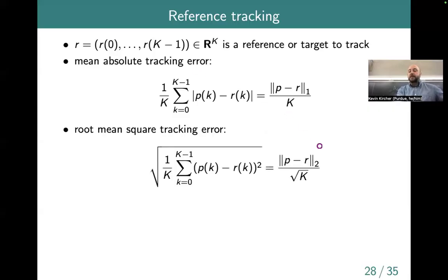Another way would be using a 2-norm approach rather than a 1-norm approach. Here we look at the error and square it. This says it's bad to overestimate, and it's also bad to underestimate, so we square it to impose a quadratic penalty on the error. Again, we add it up over time and take the mean.